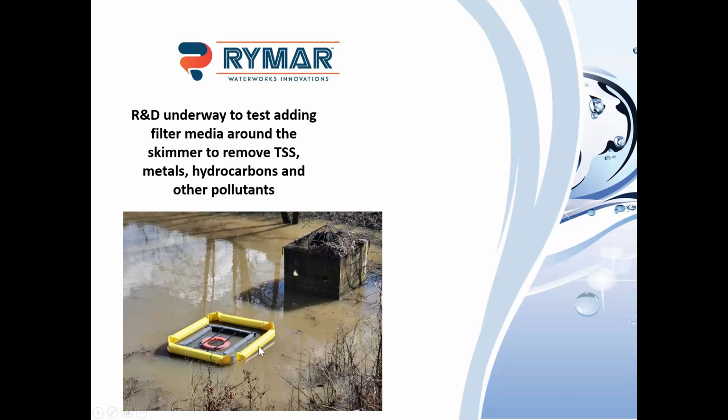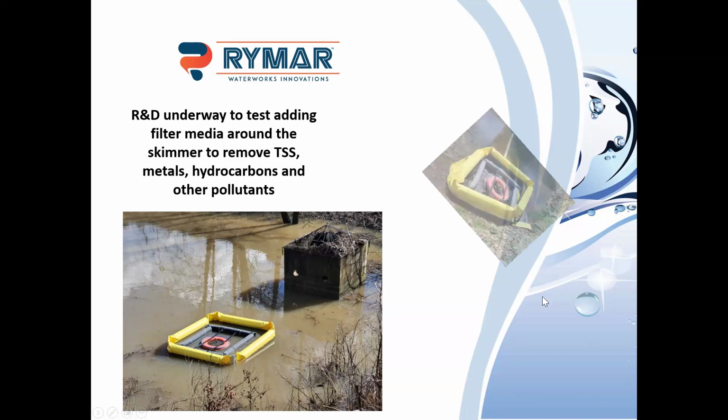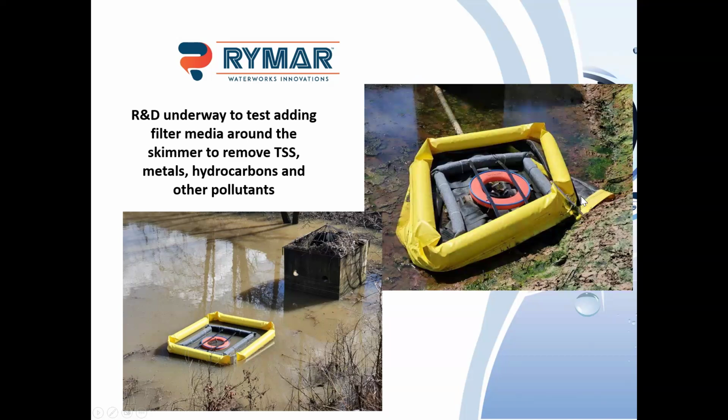We used a turbidity curtain that had a filter in the side, had a screen. It's not a solid turbidity curtain. It allows water through. And then there's your non-woven. It looks kind of like this. You can see there's your screen material in the turbidity curtain.